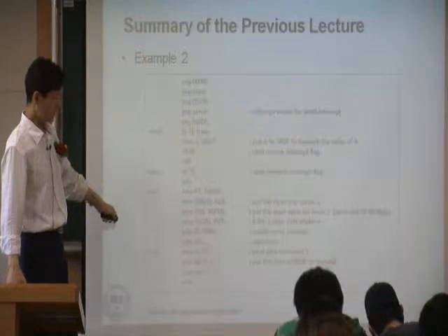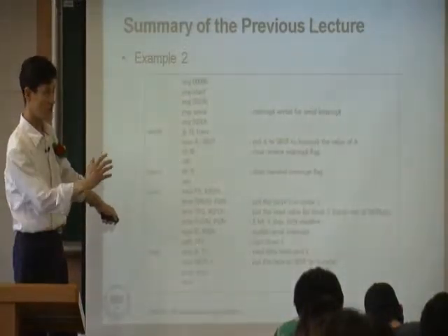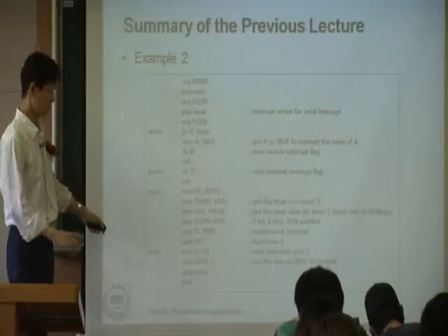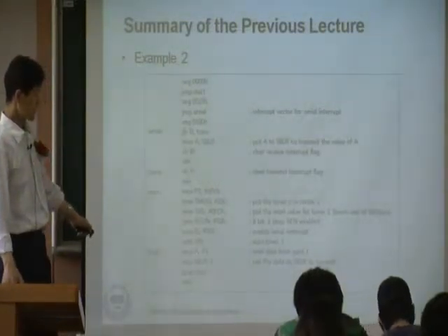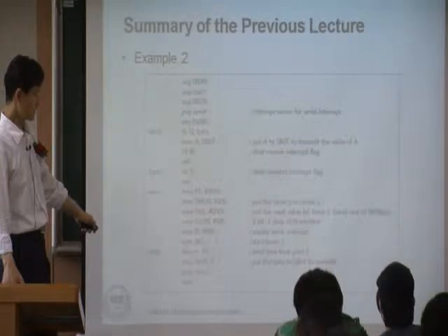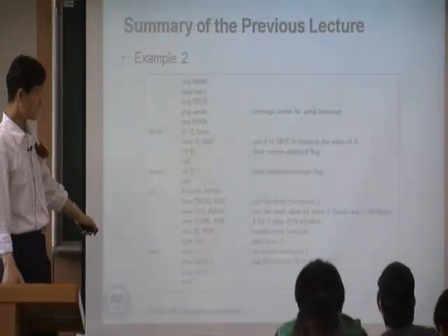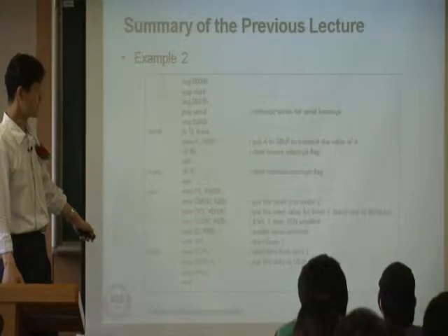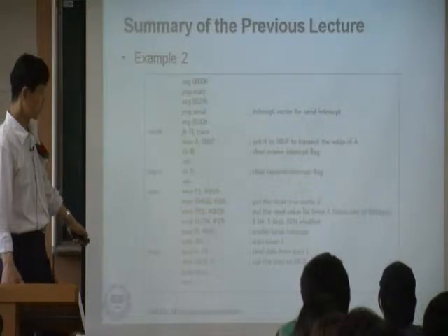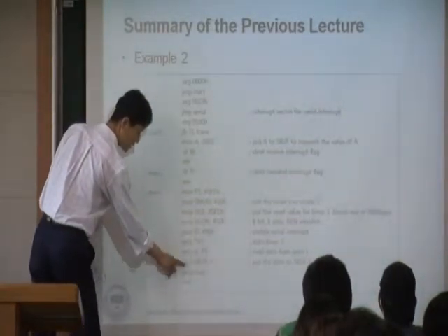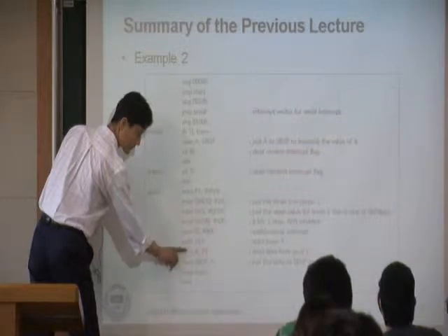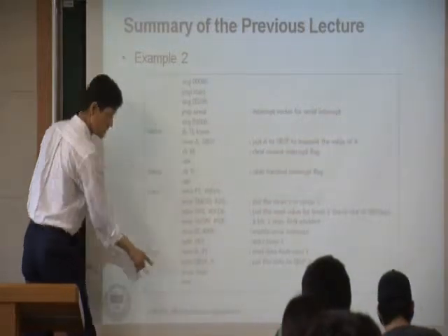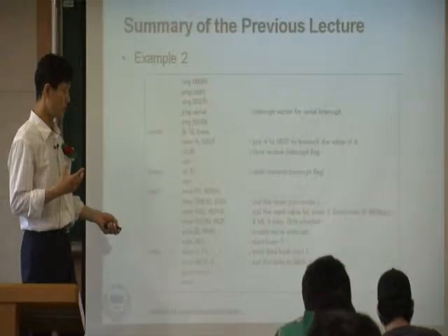And then you run the timer, set TR1. So timer is now running. Timer hardware is now running. And then right here, you read P1, port 1, and copy it into A. And the value in A, you copy it into SBUF. So you want to transmit. And SJMP loop, meaning that you jump back. So you are basically looping here. What you are doing in this loop is simply transmitting the value in port 1.